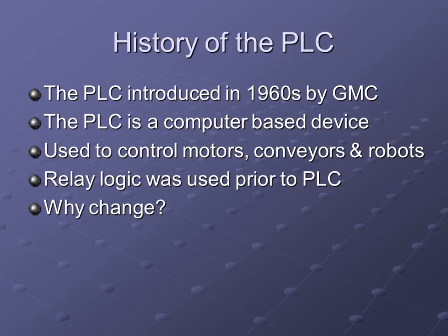It's cheaper. If I'm going to replace a whole bunch of relays and push buttons with a PLC, then that's hardware I don't have to buy. I buy one computer and it does all of the relays and control. It takes the place of all the control relays, a lot of the switches. Still got to have an e-stop. You still got to have a way to start it. But after that, we can replace a lot of it with the PLC. Timers and counters, all of those are replaced with the PLC. PLC can count. It's a computer. It's pretty smart, so it can count. I don't need a counter to do that for me. And I'll show you some of those devices shortly.